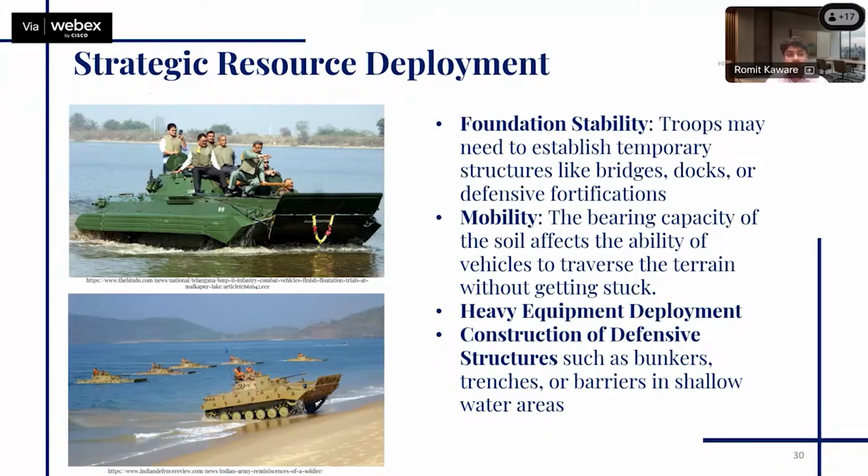So in case of deploying heavy equipment, we know the sediment bearing capacity; initial estimates of sediment bearing capacity can give us an understanding of what is the maximum load of the equipment that can be taken by that particular soil itself. Also, when we need to have trenches in a particular soil, understanding the type of sediment would be very crucial in defining the depth or the dimensions of the trenches itself.